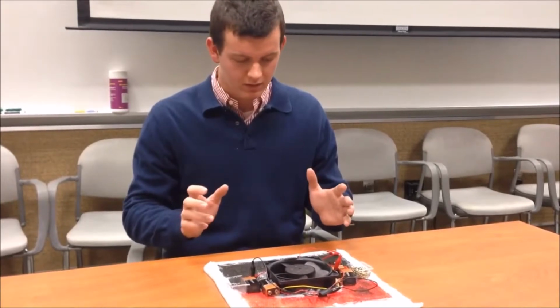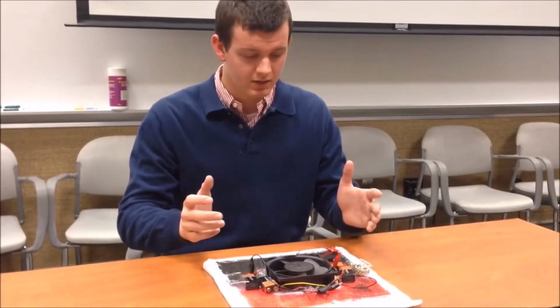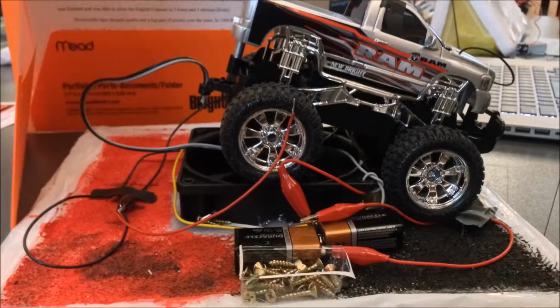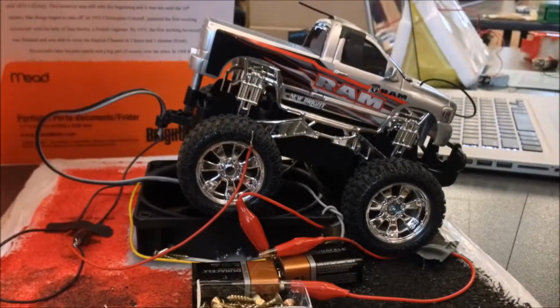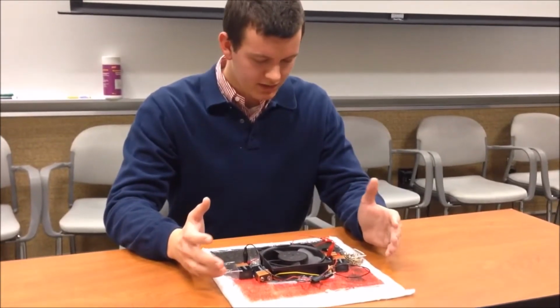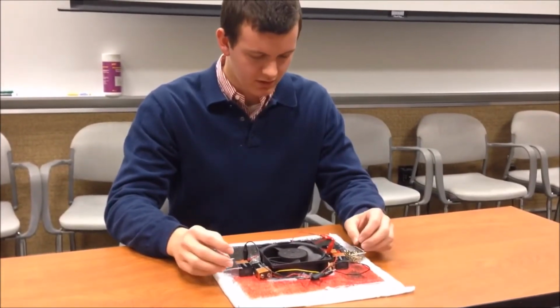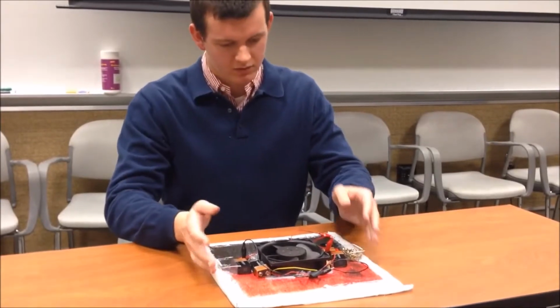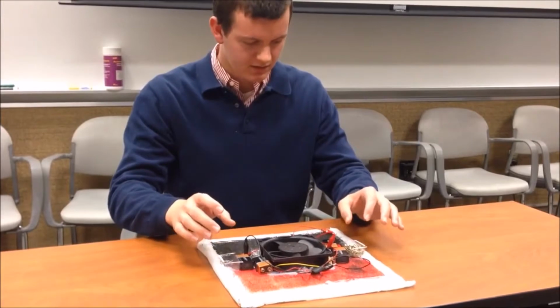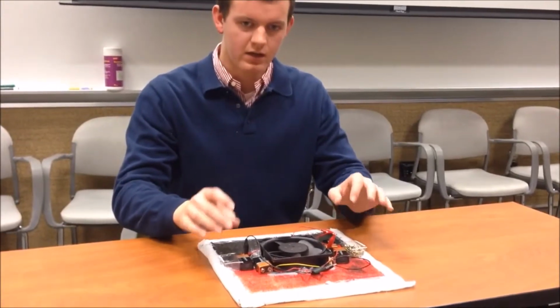So we moved the computer fans back here, and we attached paper cones pointing downwards to increase the pressure. Those didn't work either, so we went to our backup idea, which was an RC car mounted on top, which would drive off and then tow the hovercraft behind it like a trailer. Once we decided our propulsion technique, we had to slightly alter our weight distribution here because it was moving towards this way. So we attached these 2 plastic baskets here and filled weights in each side to balance our weight.